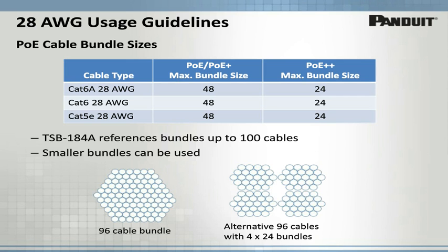And what we're doing here with the cabling by breaking it into smaller size bundles is, with the PoE being applied to the cabling, we are staying within that 15 degree C temperature rise.